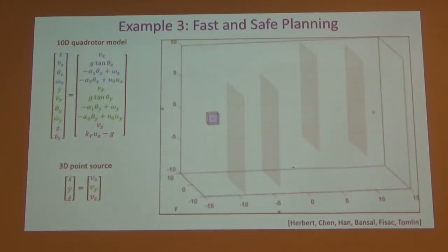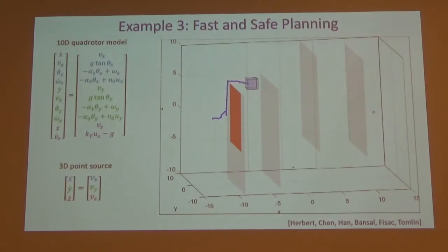So we use an RRT-based planner which senses obstacles in real time and plans a path around them using very simple holonomic vehicles. But then this robustness bubble around the RRT planner, which is this cube over here, takes that path into account and robustifies it. And finally, what we get as a combination is a planner which is fast as well as safe.